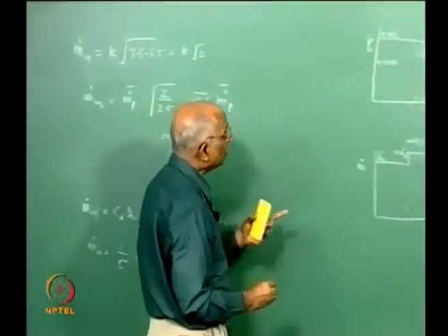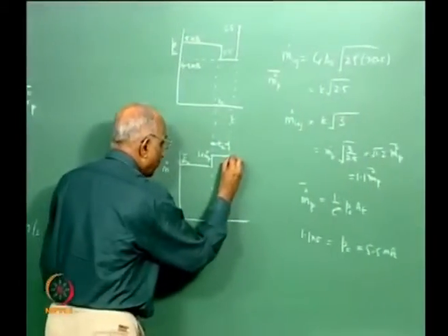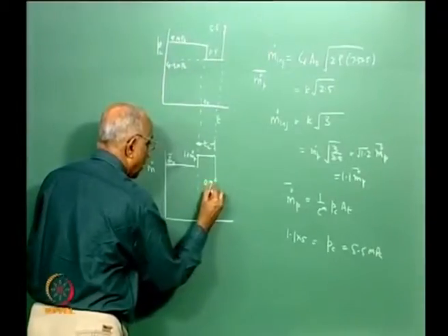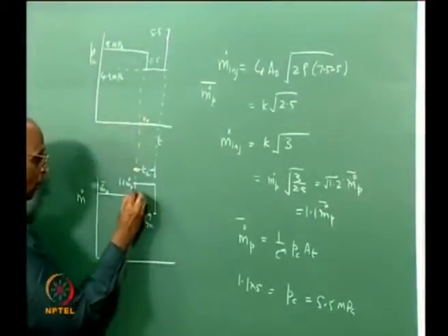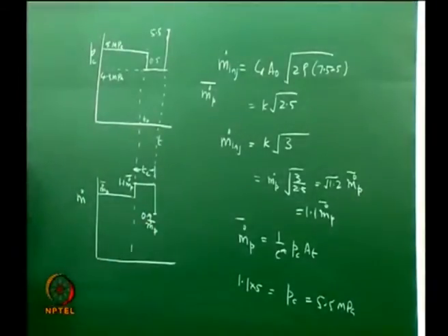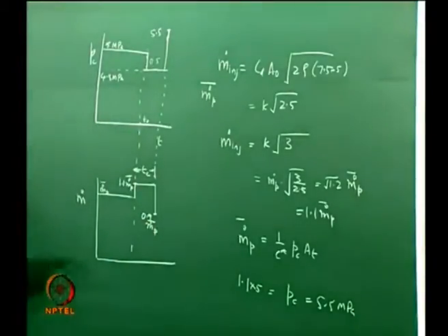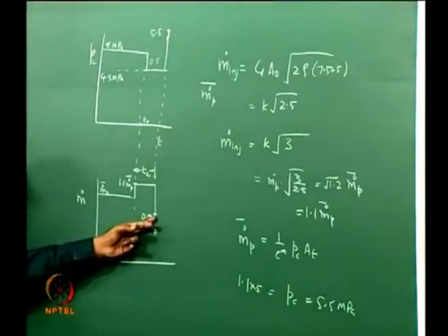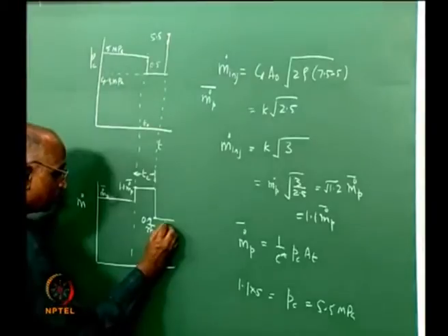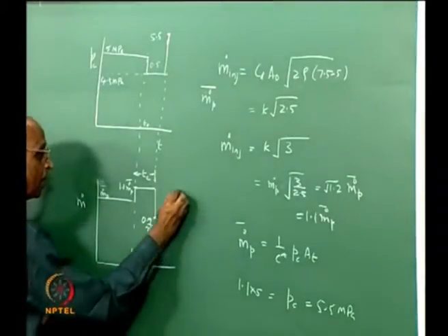And therefore what is going to happen when the pressure increases? The mass flow rate now drops to a value 0.9 of the old value corresponding to m dot p over here. Now it has come back to 0.9, and therefore this continues. This liquid evaporates, burns over a time Tc.